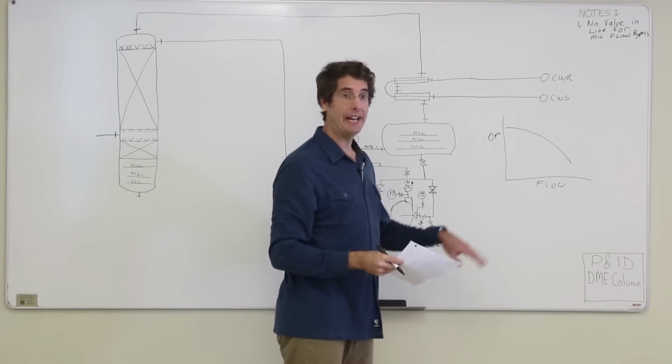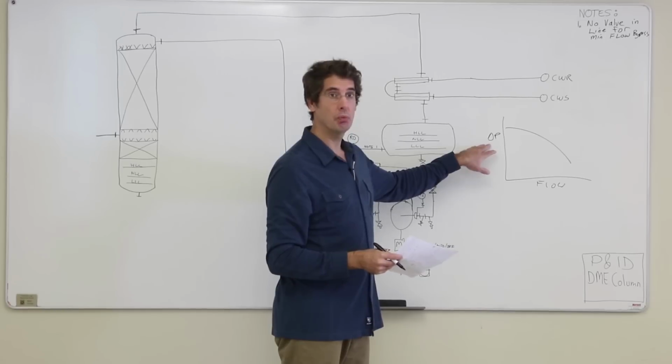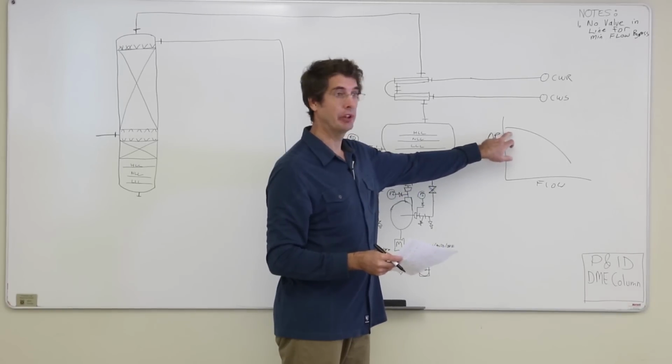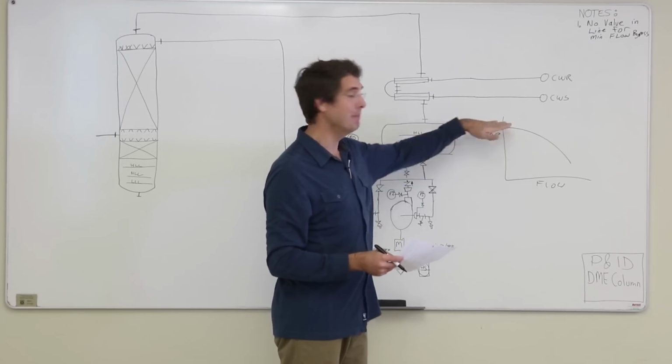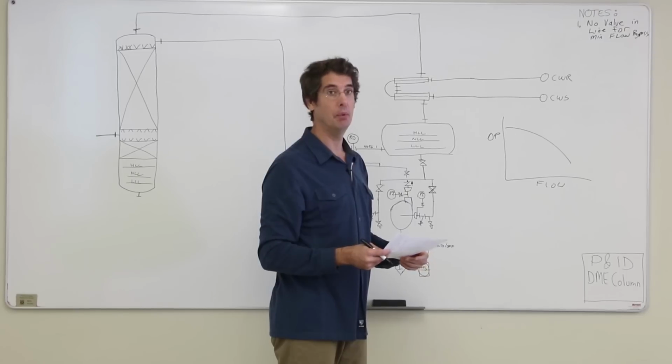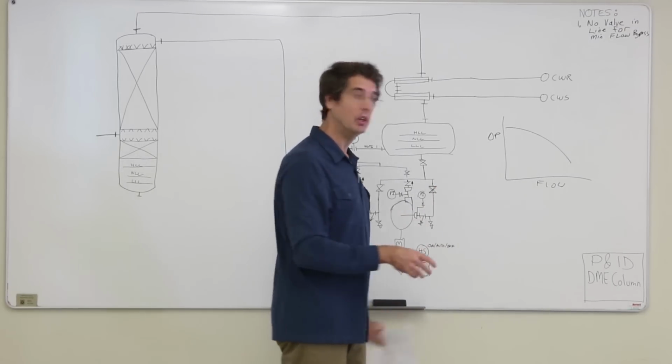And as long as the inlet pressure doesn't rise too much, then the discharge pressure doesn't rise any more than what it says on the curve. And so you should really be thinking more along the lines of designing the piping system to withstand the maximum discharge pressure of the pump rather than putting relief valves in. If you start putting relief valves everywhere, you're going to have a nightmare on your hands.